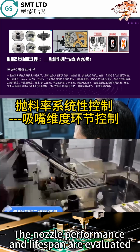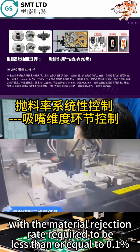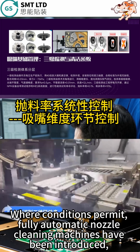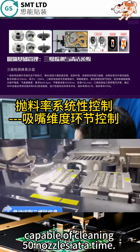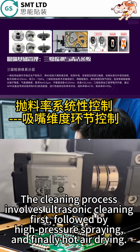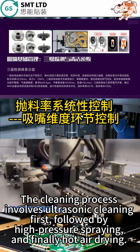The nozzle performance and the lifespan are evaluated, with the material rejection rate required to be less than or equal to 0.1% and the remaining lifespan not below 10%. Where conditions permit, fully automatic nozzle cleaning machines have been introduced, capable of cleaning 50 nozzles at a time. These machines can automatically accommodate nozzles of various specifications. The cleaning process involves ultrasonic cleaning first, followed by high-pressure spraying, and finally hot air drying.